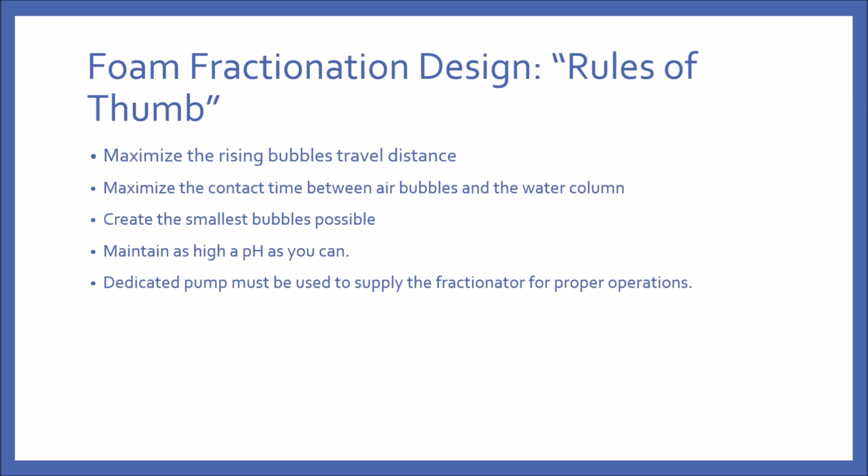You can make them out of simple PVC piping and also air pumps, or you can also use a co-current configuration where you supply the water pumps with venturis. We previously did not run the plant with the protein skimmer, and we often found difficulties getting the ammonia to 0 ppm every day. But after we have run the protein skimmer, we are able to reduce the ammonia load